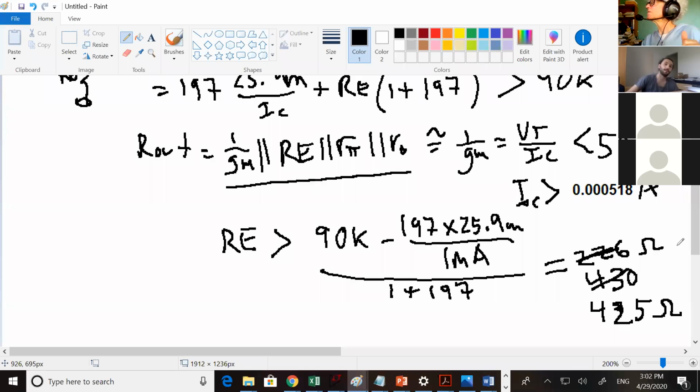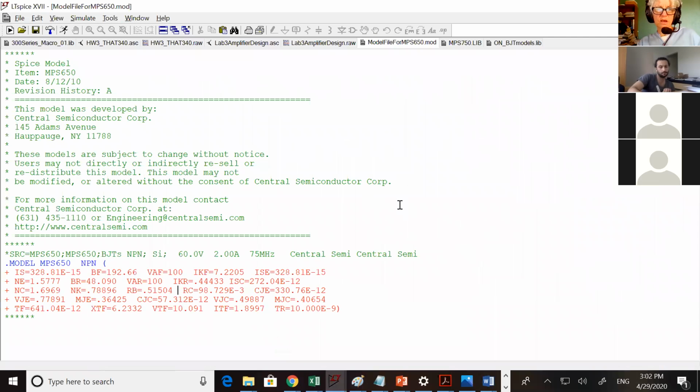So good questions? Yeah, I had a question. How did he get the beta value to be 197? How did he figure that out? That is in the model file. Oh, it was given to you in the first place. Okay, that makes sense. Yeah, so if you go back to the MPS 650, this VAF, that's your early voltage, that's your beta, your VJs, your VB on if you need it. So you can get those values from the model file.